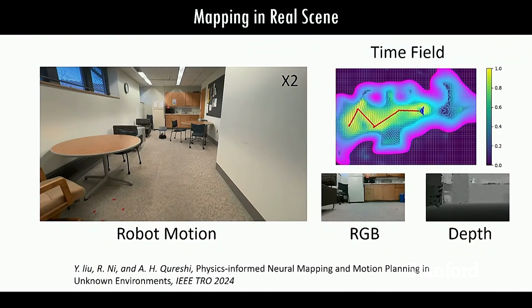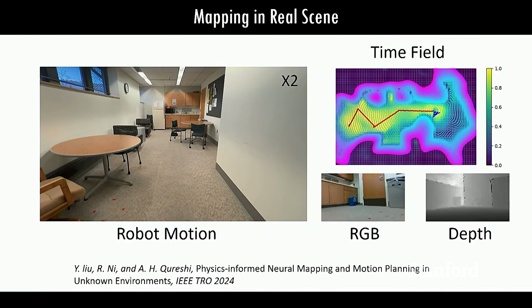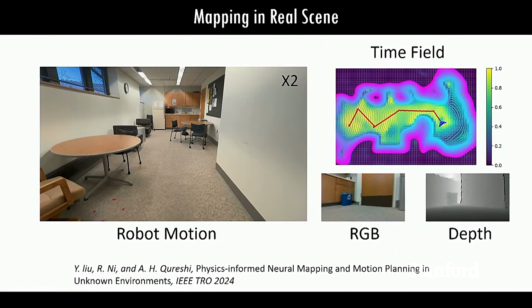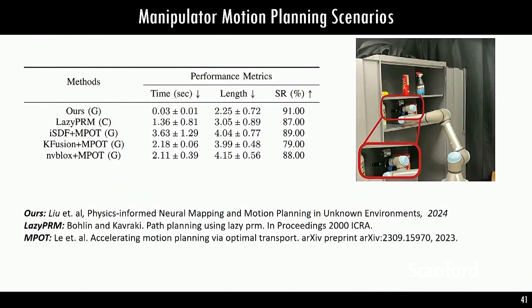If we can get these maps in almost the same amount of time as your occupancy map, then you don't need any motion planner. You can just deploy your robot anywhere in an unknown environment, and it will figure out how to move in that environment with these plug and play models. Another advantage is that you can even do manipulation with it. You can equip the robot with an in-hand camera, and it will explore and construct these arrival time field maps in C space, and still navigate.